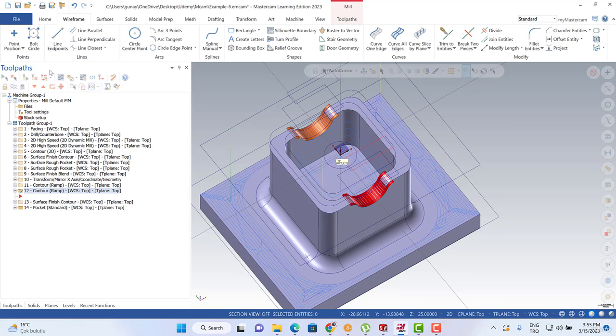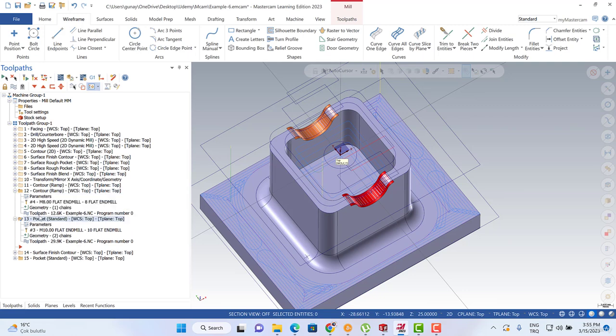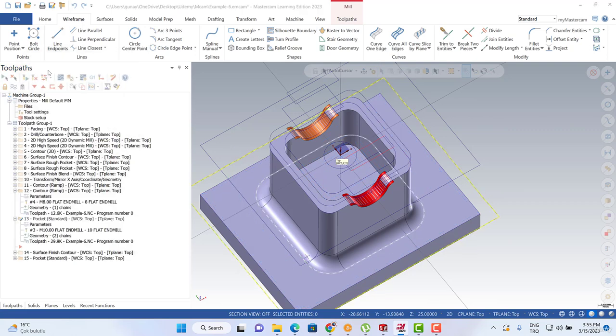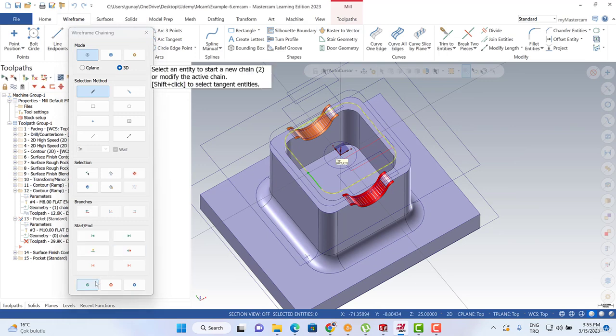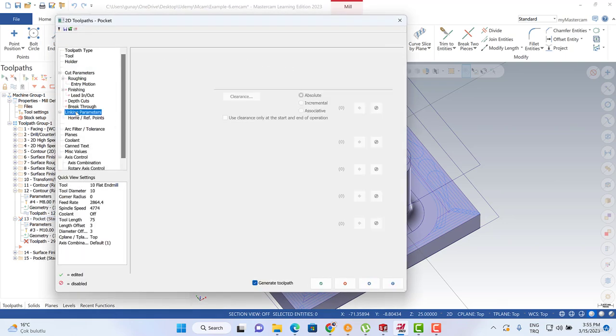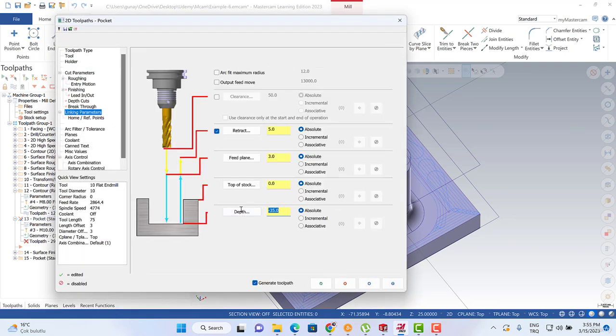And after that, of course, as a final step, we can also copy that toolpath and paste it here. Okay, and this is the 8mm tool. We can turn to here and delete this one and add new one. We can select that one and hit the OK button, and the linking parameters can be -25.